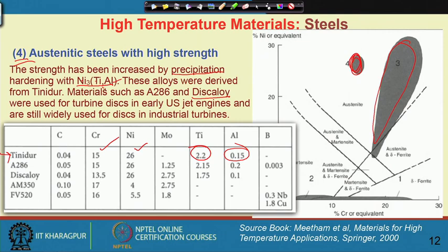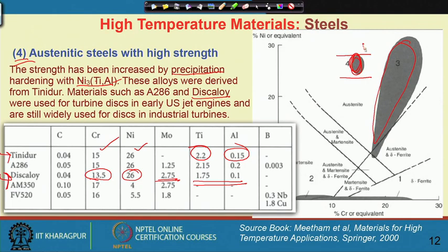which give us a higher strength at an elevated temperature. And also the disc alloy, you can have a look, has a reduced chromium but the same nickel content with a slightly higher molybdenum, because people expect some precipitates of molybdenum and so on along with those titanium aluminides. So, this is very specifically designed with a very well-chosen composition range that engineers use